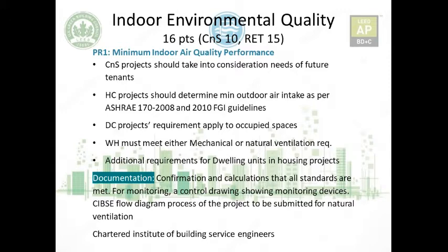When it comes to healthcare projects, usually they have stringent measures, and the requirements are generally high. So it should determine minimum outdoor air intake as per another ASHRAE standard, that is 170-2008 and the 2010 guideline. For data center projects, requirements apply only to occupied spaces, because generally the same amount of ventilation would not be required for equipment. So it is basically for people, and it would apply only to data center projects where there are occupied spaces.